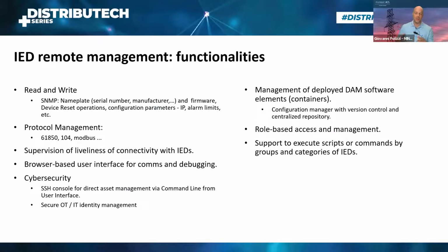So what's the IED remote management? In more detail, what are we doing over there? We're doing read and write on those devices. We're doing the protocol management. We're doing the supervision of liveliness of connectivity. One of the problems was basically that when you lose connectivity with the IED, they didn't know if it was actually a problem with the IED or just a connectivity problem. So the OneSide platform and OneSide Things basically work together to make sure that there is a supervision of the connectivity, of the liveliness of this. We give a browser-based user interface for comms and debugging of the IED. Of course, we implement the cybersecurity directly in the device asset management tool, as well as in the platform.